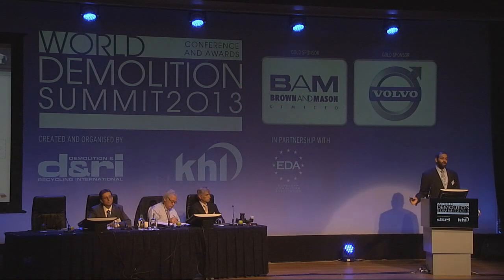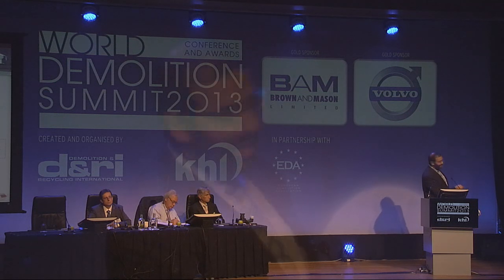And then we can check for lateral loads, wind loads, seismic or earthquake loads. And then we can go and apply the demolition scenario. And at all points along this stage, when we're doing the analysis or running the different scenarios, we always go back and check the performance measures. Okay, does it satisfy the performance requirements or not? And then we can go back and modify if necessary.